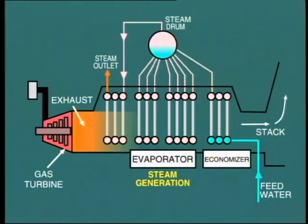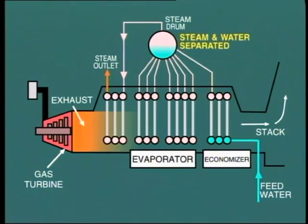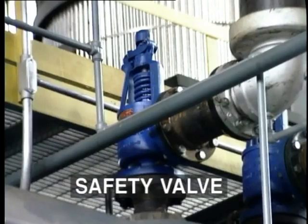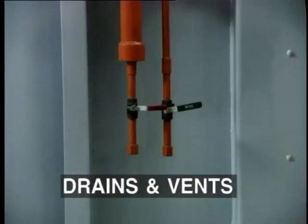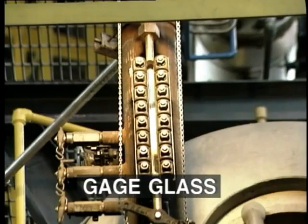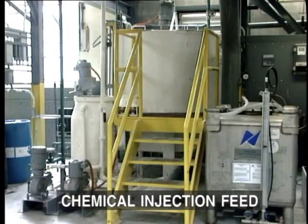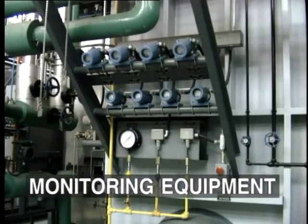The steam-water mixture returns to the drum where it's separated. Steam then passes out to the superheater where additional heat is added, and from here it flows to the utilization equipment. Also, similar to the fired boiler, auxiliary devices and equipment are fitted, such as safety valves, drains and vents, gauge glasses, water level controls, continuous blowdown line, chemical injection feed, monitoring equipment.